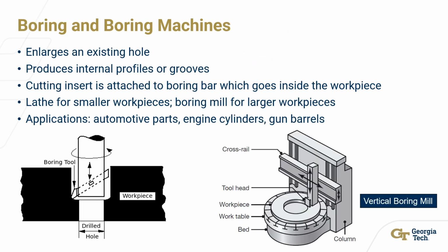Another topic that I found interesting is boring and boring machines. Boring is the process of enlarging a hole made by a previous process. It can also be used to produce internal profiles or grooves in hollow workpieces. Either way, a hole must already exist in the workpiece. Boring can be done using a lathe or a boring mill to guide the position of the boring tool, depending on the size of the workpiece.